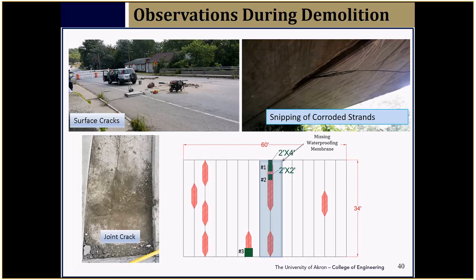I might ask you a question. So when did we change? Because there are different types of membranes. We have changed. Like I said, we keep putting the membranes down and we waste our money putting them down. You guys understand construction. To pave asphalt on top of the membrane, when you're entering with your paving equipment, it's all aggregate. So you don't have your approaches, your box being prevented. So how you get your equipment up there is impossible. And then the tack is not cured, and you put 200-degree asphalt on it, so you can say it's not trackable.